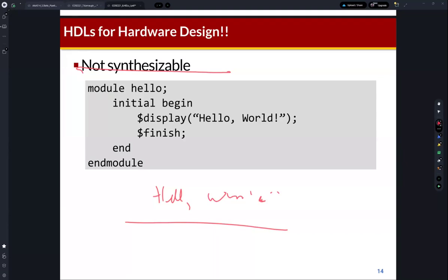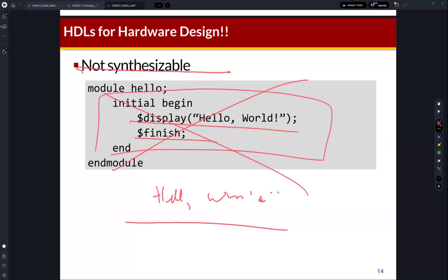It's just a software execution and simulation, but it's not synthesizable. We can use this code because we can simulate our code and debug our HDL code. So we can use these unsynthesizable representations. It is required actually for debugging. But you need to remember that this code is not synthesized. So it means that we cannot build the correct hardware using this code.